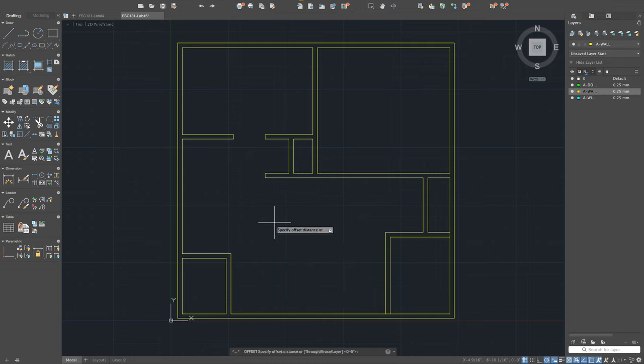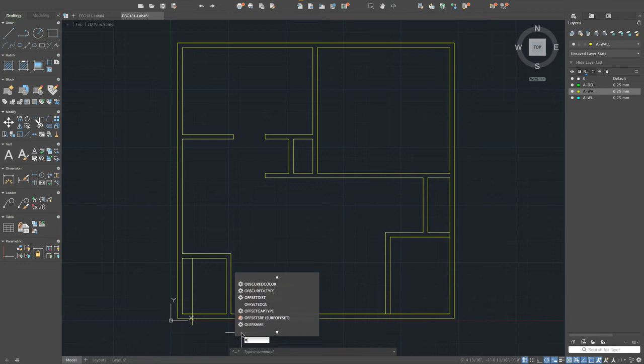I'm going to offset this line by 11 inches, this guy, see? Then this is where the door normally starts, right? And the size of the door is 3 feet. So the way you can proceed, let me extend it a little bit, and then first you can create the opening, and you use offset again and use 3 feet for the opening.